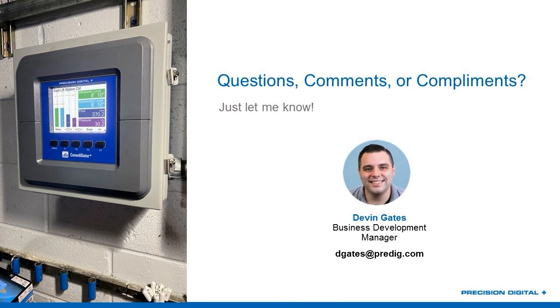Like, for example, I can tell the ConsoliDator Plus what I consider a signal break. So usually that would be 4 milliamps, right? But let's say, for example, in this application, you want the break to be under 6 milliamps. Well, then I can have the ConsoliDator Plus report a break, and we can do all sorts of alarming and scheduled events based on that. So if you want more details, I'm happy to get on the phone with you and discuss this particular application, but I can confidently say, yes, we can do that.